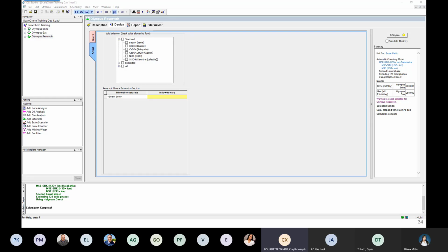But as I'm calibrating the model, I will ignore the solid formation to see how close the model that I'm trying to build is to the field condition, and then add the solids to benchmark my model, which I will then use, based on the deviation that I allow myself as the user, for evaluating, or let's say predicting, the scale formation. Is that correct?